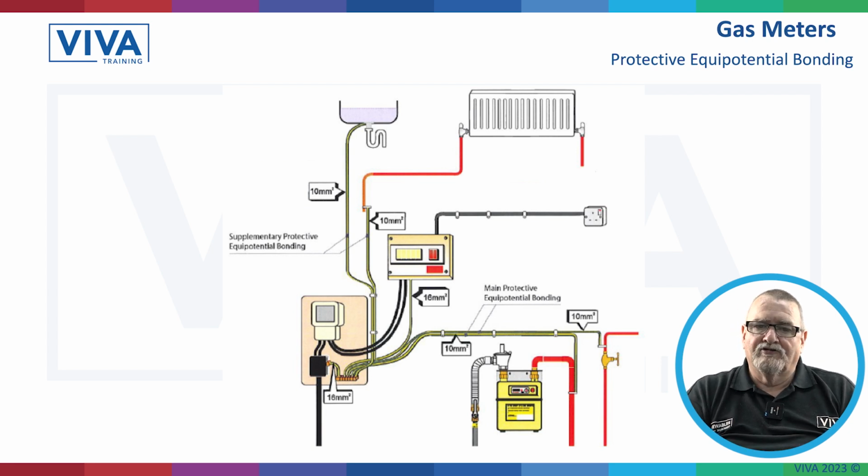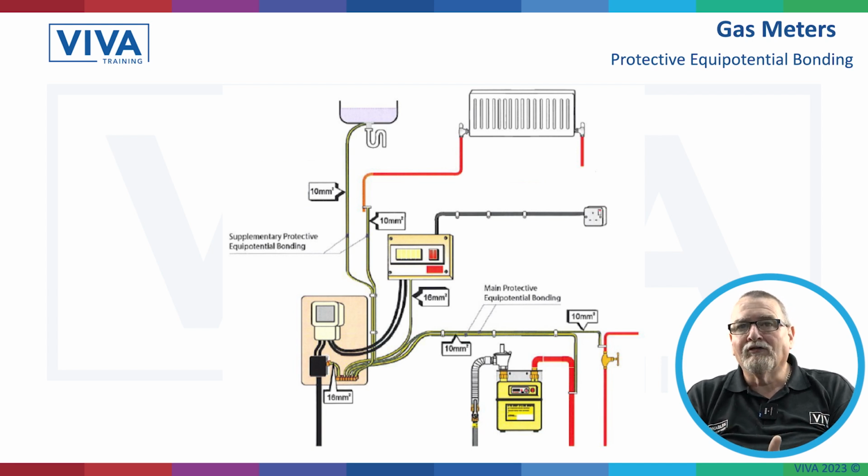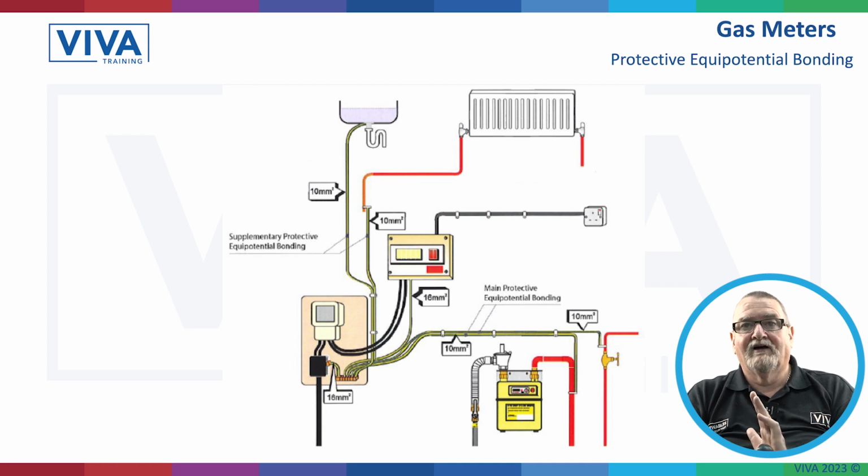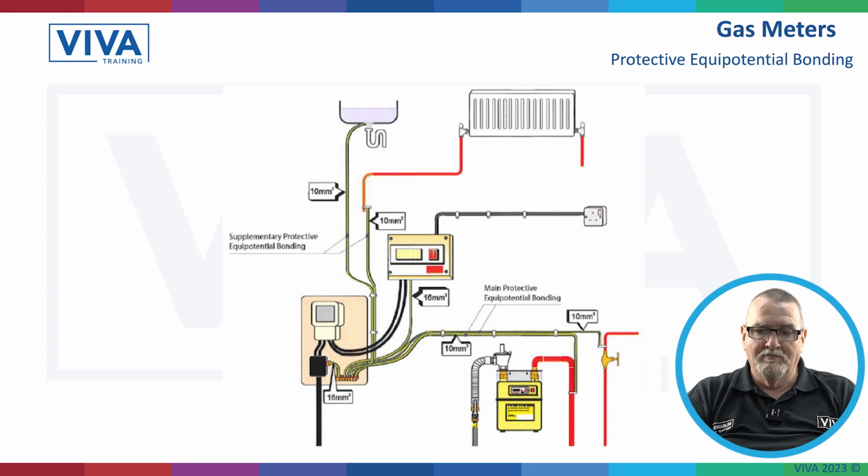So it all goes back to a British standard, BS 7671, and that came out in 2018. Requirements for electrical installations. Now we're gas engineers, so we work to the gas regulations. Electricians work to the IET wiring regulations. And in clause 554.1.1.2 it refers to metal installation pipework supplied by metal service pipes. Now modern service pipes tend to be plastic. We still put equipotential bonding on there, even though that service pipe is made out of PE, polyethylene plastic. We still have potential there because the gas pipework is made out of copper, the meter's copper.